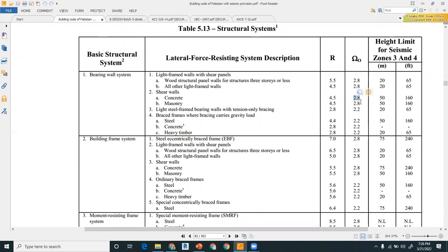Normally, this concept is not clear to some students. For example, if a student wants to design a member or a wall, column or beam to remain elastic throughout its life, you have to use this strength reduction factor, and it will be designed accordingly. In the UBC code or the Building Code of Pakistan, there is no definition of the strength reduction factor in ETABS, but in the new code, ASCE 7 gives you a free hand to give any value of the strength reduction factor when you are designing for earthquake forces, right?